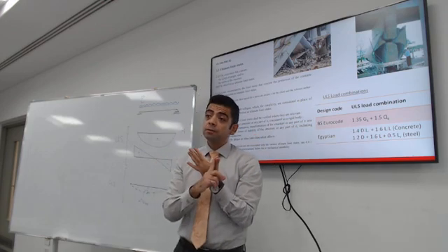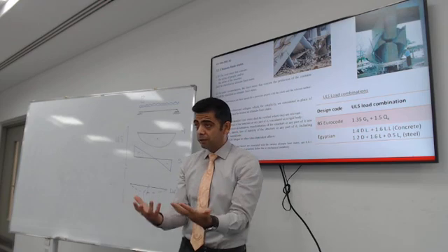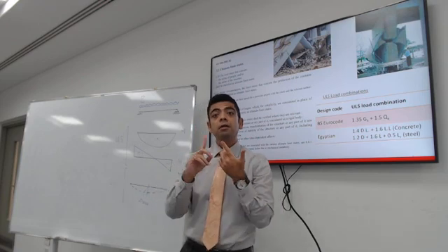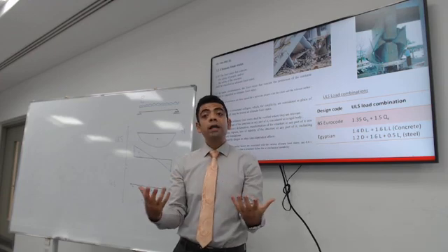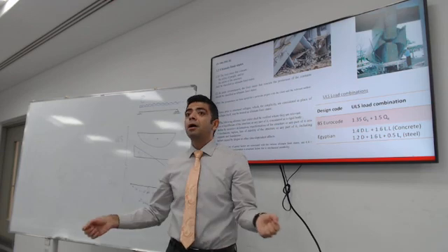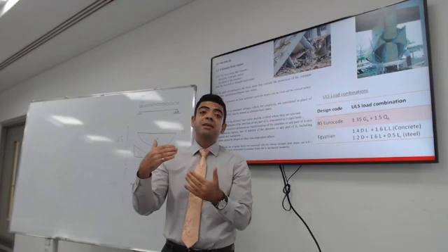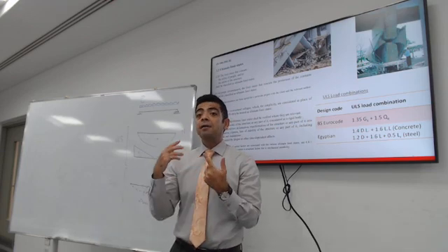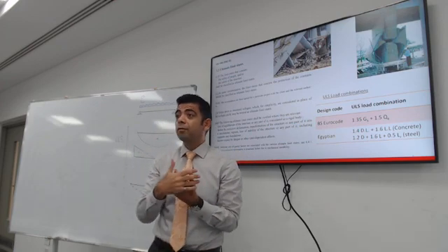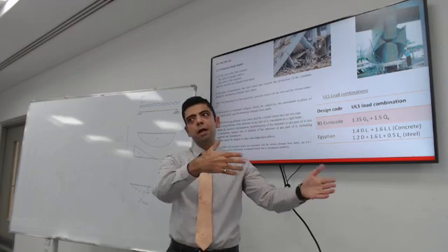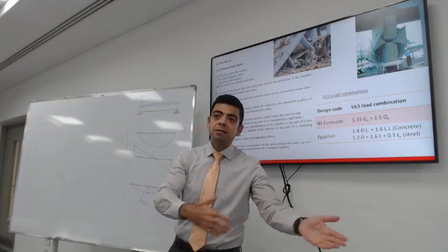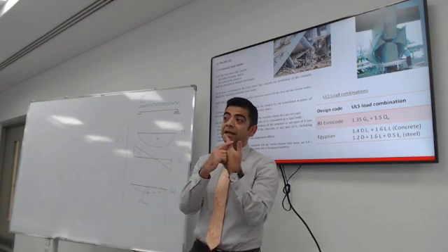The dead load, that includes the self-weight of the structure and anything that is permanently in the structure. The live load, which is the weight of the users, us, our furniture, our luggage, anything that comes in and out of the structure. If that structure was a parking structure, the cars would be the live load. Cars in the morning, people are going to work, they park in the parkade. At the end of the day, cars leave. So that's the second type.